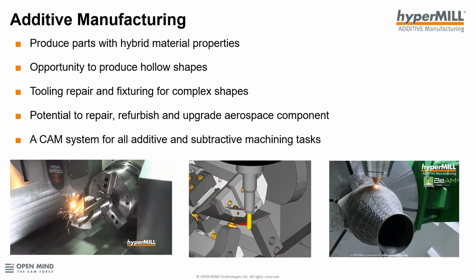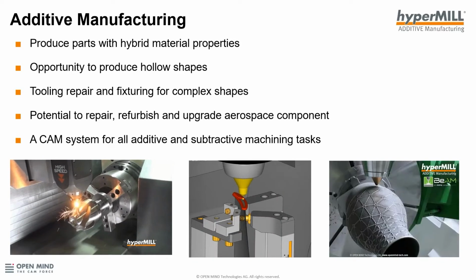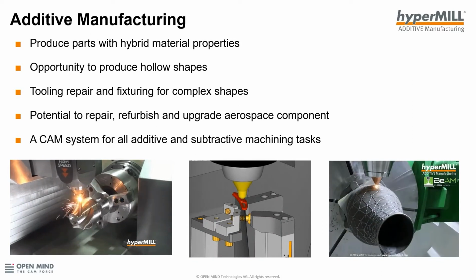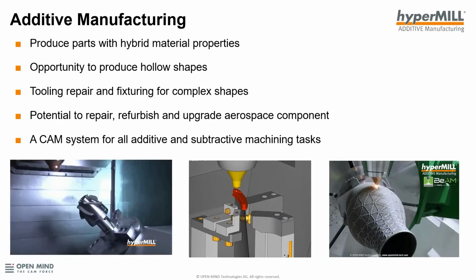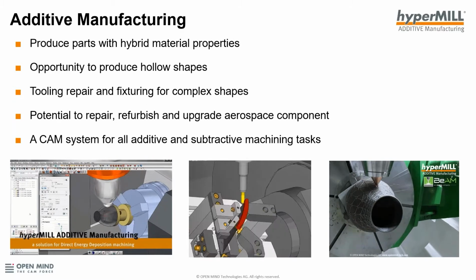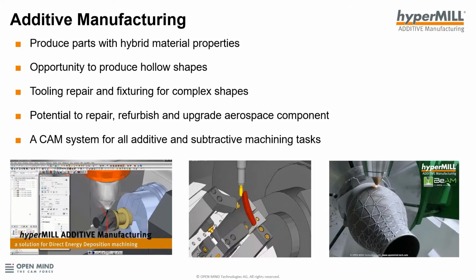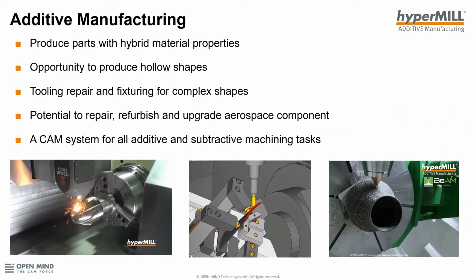additively manufactured. So with additive technology, especially for aero engines, there's an opportunity to produce hollow blades, which has its own advantages. People who are into blade manufacturing know, of course, they are lighter, but at the same time you can have the same aerodynamic properties.